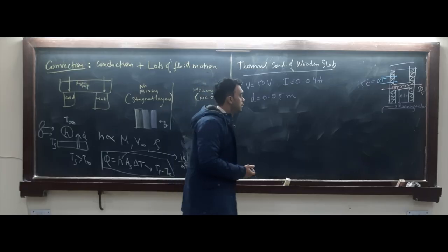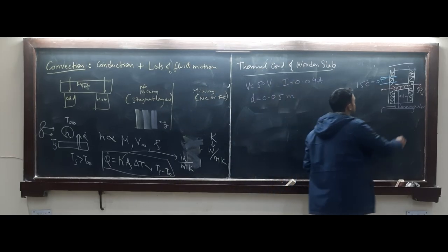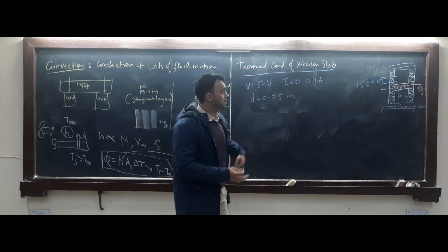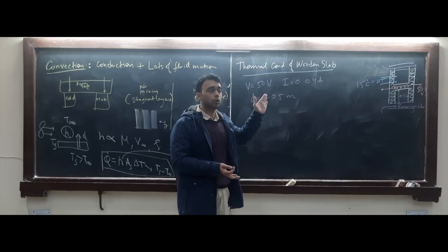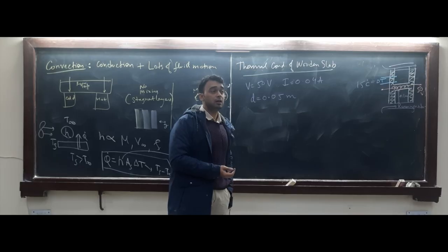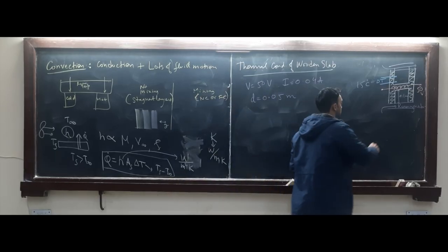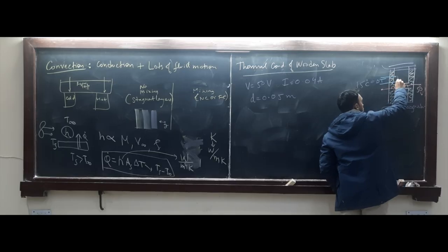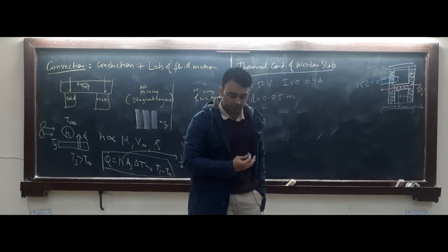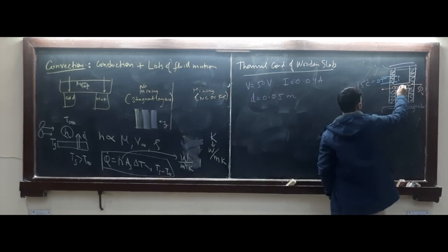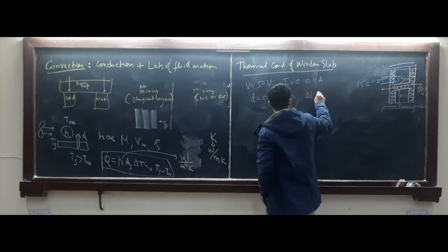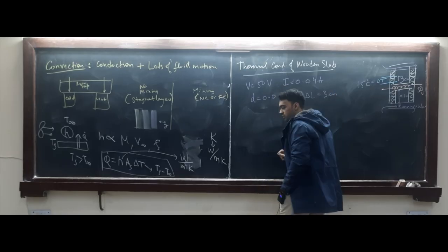What else do you need? Running water is here, so the conditions are symmetric in top and bottom. Thermocouples are separated by a distance, so don't take 0.1. So would you need the information how much is this? Right? Because that is your delta X or delta Y. This is 3 centimeters, 0.03 meters.